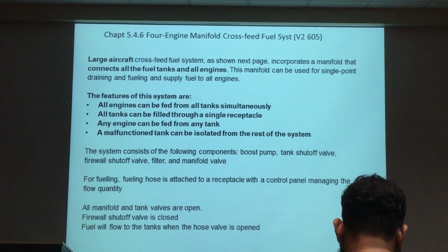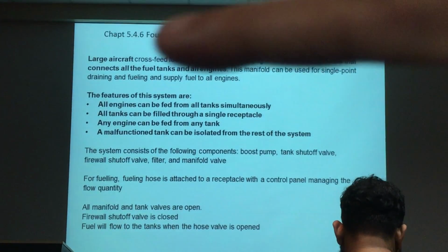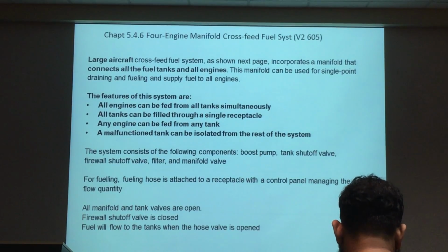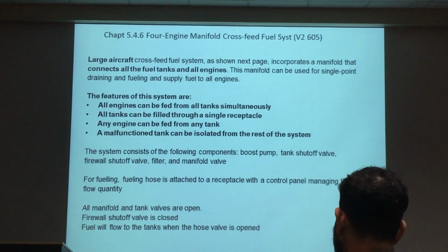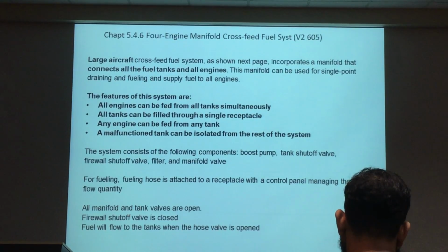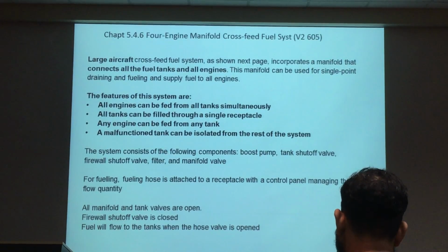During flight, all your fuel will contain air bubbles. Okay? When your fuel is burning, the supply will not be constant. It can go off anytime. So it is no good. Okay? But some people will ask, what about gravity feed? Gravity feed is no choice. It is only when all the pumps completely fail, then you talk about gravity feed. Okay? That is fuel safety. There is no choice. Okay? But in normal design, you might have at least one pump working and enough to provide pressure for all 4 engines. So this is a design requirement.